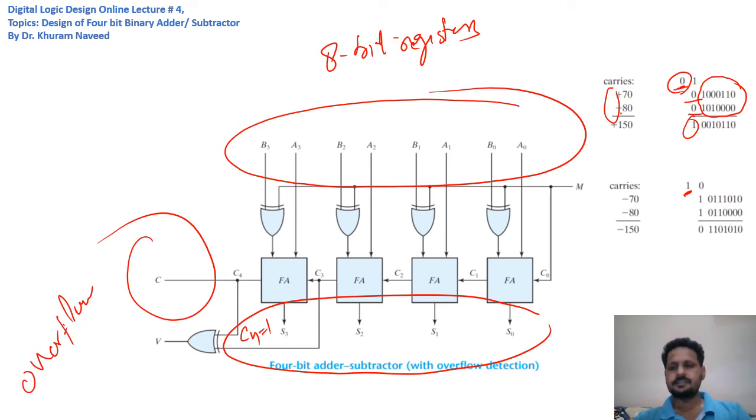And this time, the transfer of the sign bit is not because the addition has expanded to 8 bits, but because the two sign bits are 1, and when we add them, generally its sum is 0, 1, 0, and the 0 comes in the location of the sign bits, and the 1 goes to the next location, right? So here again you see the transfer of the sign bit to the next location, right?